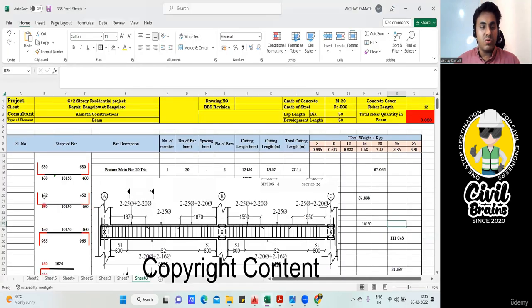Now I know 57 times the diameter of the bar, but remember one thing: whenever we provide the beam reinforcement, we don't take this bar completely from the outer of the column to the outer of the column. We never take it. Why? If you take it, your bar will be exposed to the atmosphere, and corrosion is going to happen. So always we leave a cover, right? Since this bar is going into the column on both sides, we need to deduct the column cover from both sides.